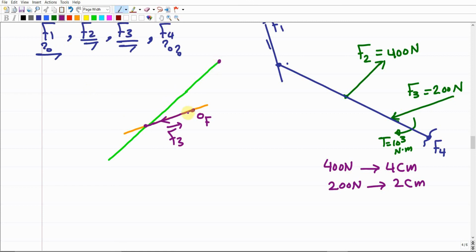So it's gonna give me this point. Then your objective is just to connect these 2 points together. This is gonna give us the F2. So remember, since we are calculating, here we are not doing analysis. We're just finding the resultant of 2 forces. This is different than the analysis that we did before.